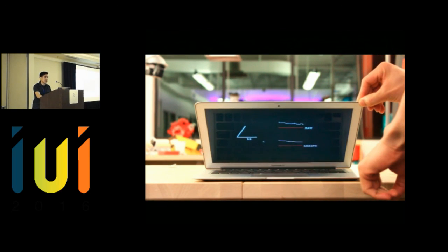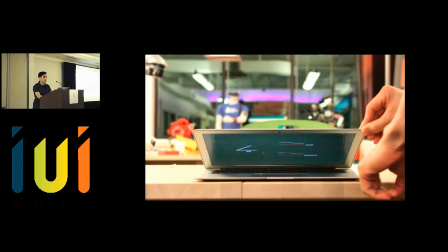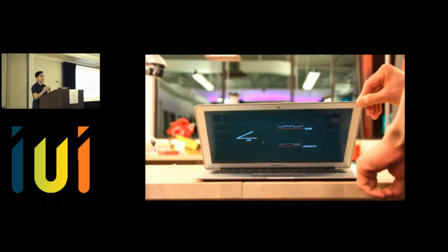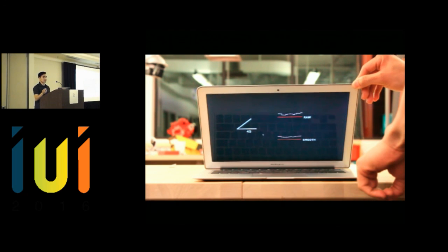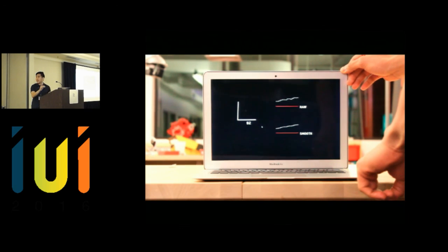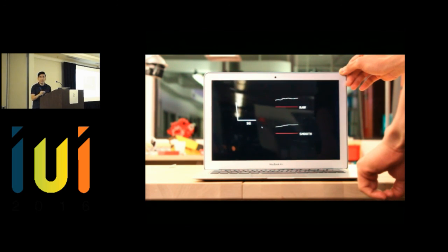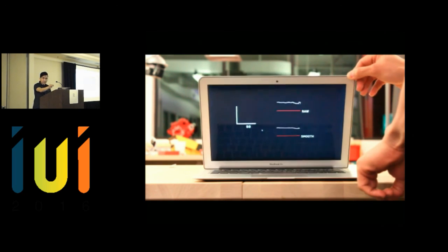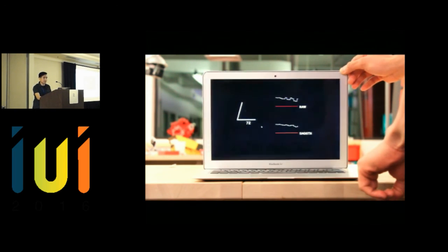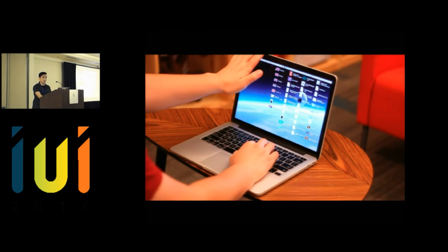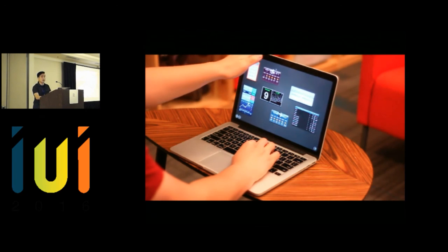There's another example where we use a laptop's integrated speaker. Changing the lid angle changes the reflectance behavior of different acoustic frequencies. And then we use this data to train a regression model, which can then act like a lid angle sensor without extra hardware. This could be used, for example, to switch between different interactive modes. For example, tilting the screen can trigger a dashboard. Also, our evaluations show that our model can be within 4 degrees of the correct angle.